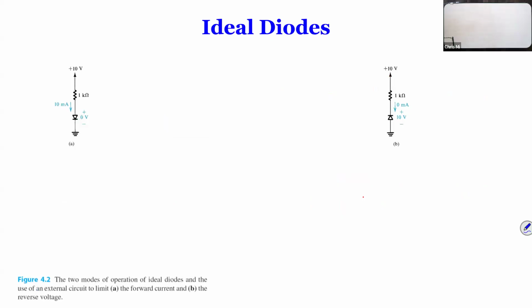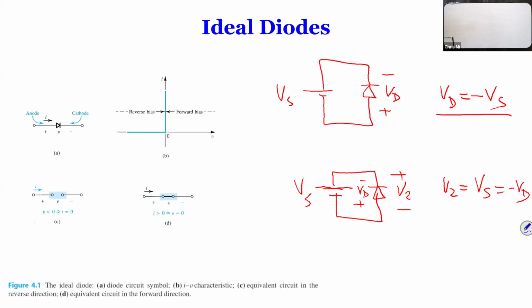Yes. Does the diode hold that voltage? The ideal diode in the reverse direction, yes, it would hold any voltage. So it kind of acts like a capacitor. Yeah, you're right, it is similar, but it's not a capacitor. It's blocking. There's some similarity, but a capacitor would store the energy, and this does not store any energy.